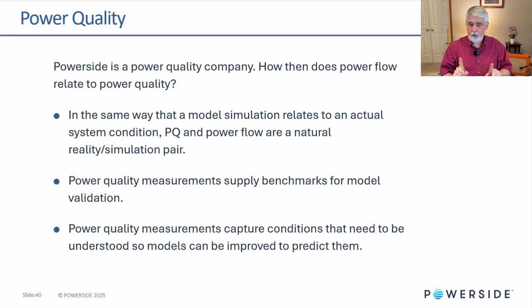For example, power quality measurements can help supply benchmarks for model validation. If you have a measurement and you know what the conditions are for voltages and flows for your pre-event condition, you can simulate in the power flow and you can match it and say that you met a benchmark. This gives you a lot of confidence when you're moving forward in your simulation work.